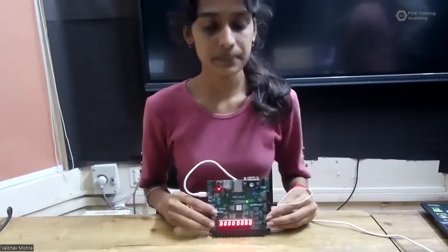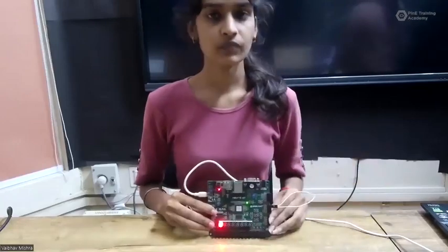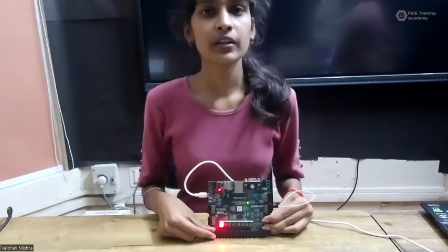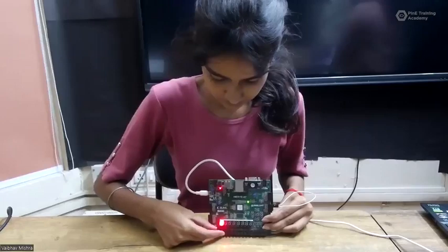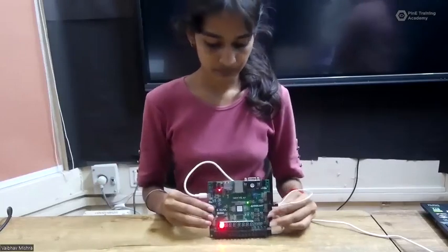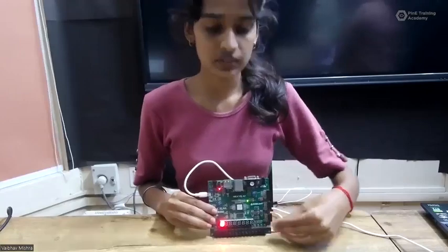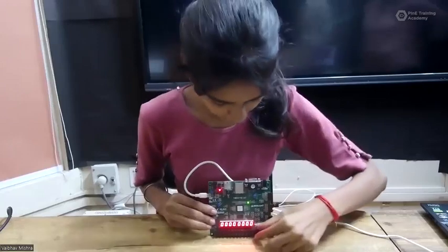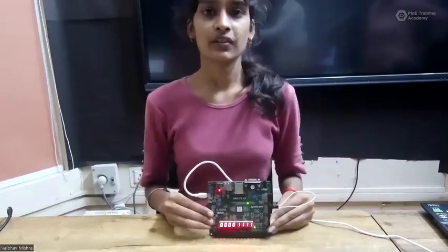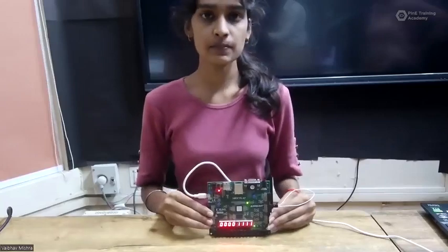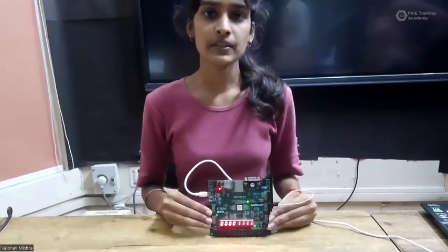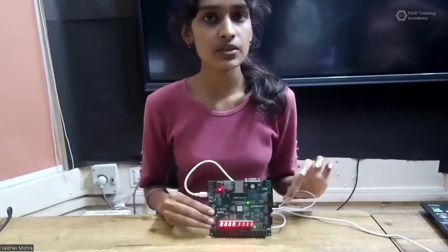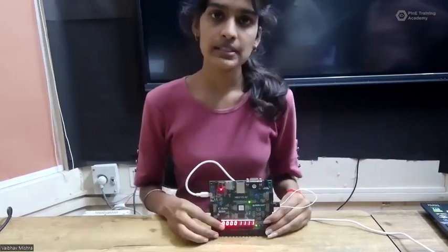Now, first of all, we will raise the reset pin. After that, we provide the parallel 8-bit data inputs. Here I am providing four consecutive ones and four consecutive zeros. Now, again, I am lowering the reset pin. Now I'm starting the transmission and the reception. When I start the transmission and reception pins, we get our transmitted data, which is transmitted serially using this jumper cable, and received serially using the other end of the jumper cable. And the output is shown on the 7-segment display.